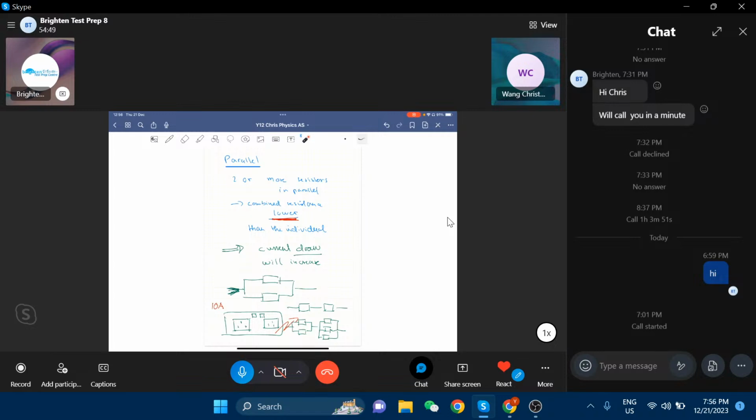So that could be a typical question of what happens if you misuse and start to integrate such parallel circuits. First, you have to realize if you plug in more sockets than there should be with these multipliers, it results in parallels. As a result of that, the resistance goes down. In consequence, the draw goes up, and it may be too much. And hopefully, it's properly wired and the fuse blows.